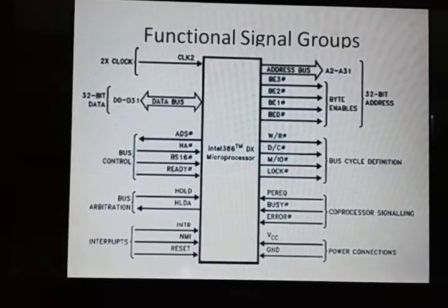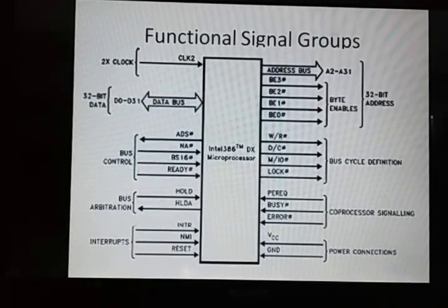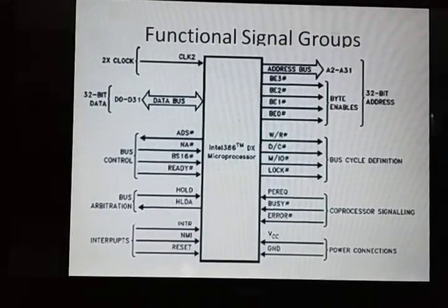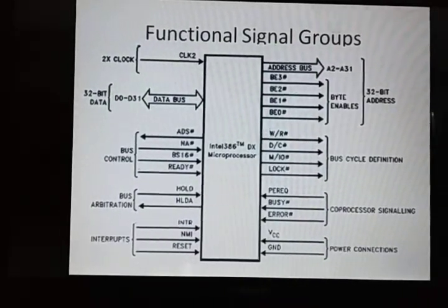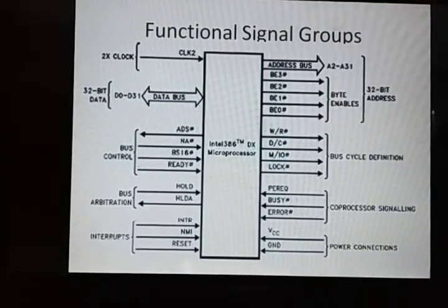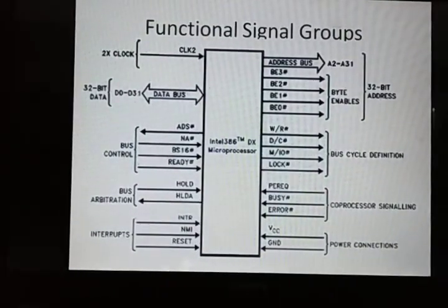So what does the ready pin indicate? The ready signal indicates to the CPU that the previous bus cycle has terminated and the bus is ready for the next cycle. Your next pins are the interrupt pins, and we say the interrupts are INTR, NMI and reset.